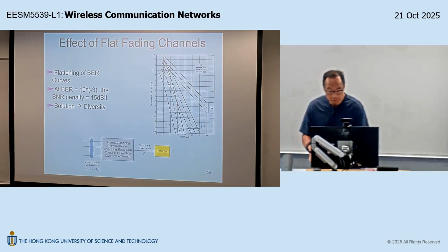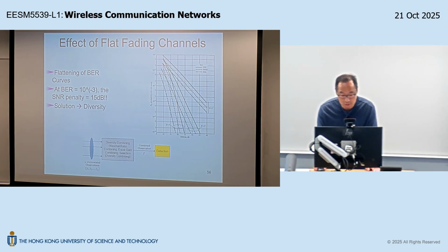So we will continue the discussions. Just to recap a little bit. Last week we were talking about the first-order trouble, right? The trouble introduced by the frequency flat fading was that the error probability curve was decreasing as we increase the signal-to-noise ratio, but decreasing slowly, right? The first-order penalty is characterized by the slope, and the slope is very small. So therefore, the solution roadmap is to exploit diversity.